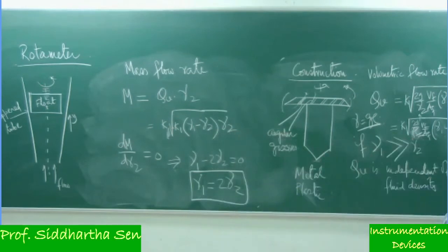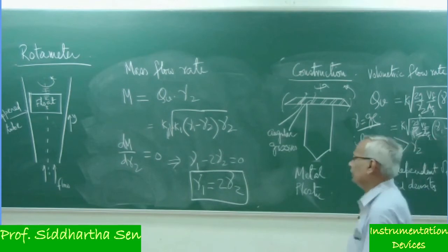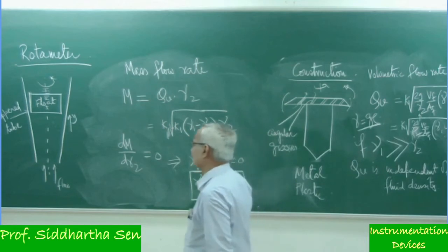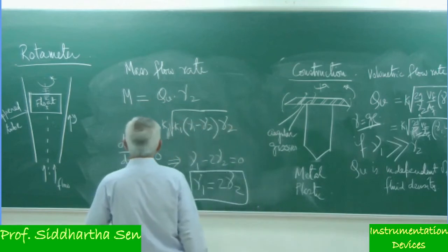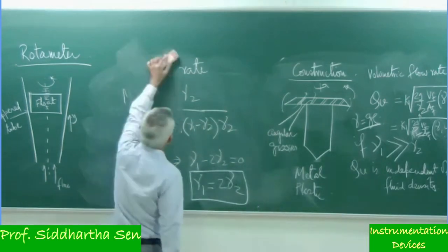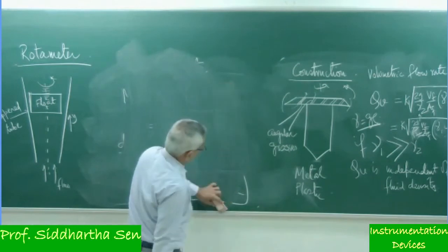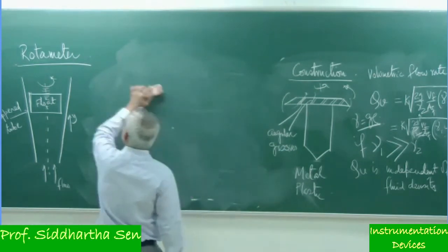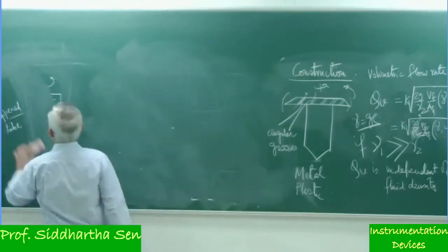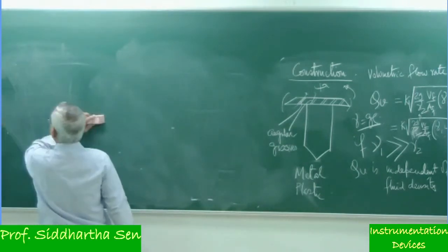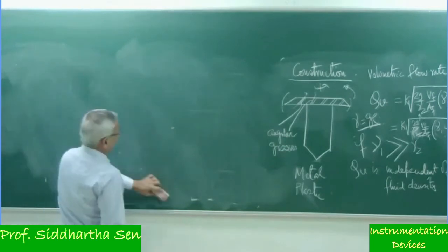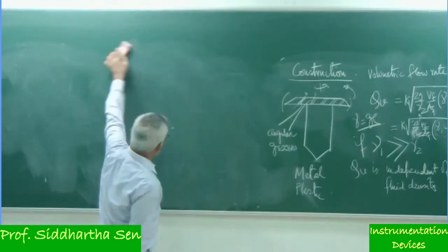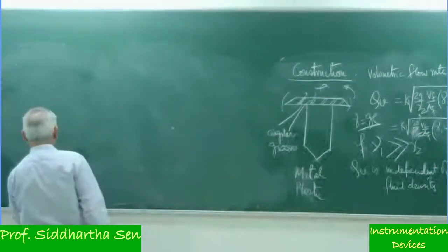So always in any plant, for visualization, we will find a rotameter connected to it. Okay. But it must be held vertical and the float has to be designed properly.